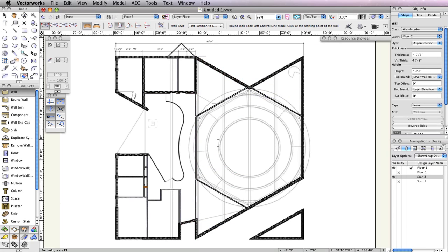As you're tracing the walls, press the U key to cycle through the wall alignment modes in the toolbar to make tracing easier. Additionally, don't forget to use the Snap Loop to get a closer view when necessary. Here's what you should have once you're done. For the last set of walls in the lower left rooms, we need to use the Split tool and the Wall Join tool to create openings.